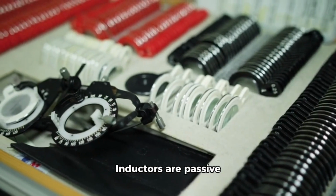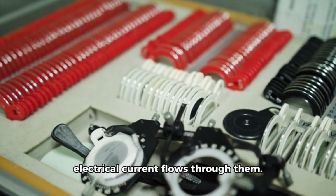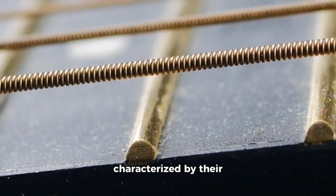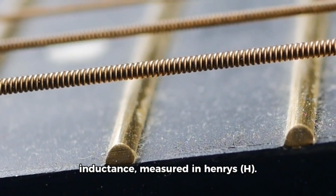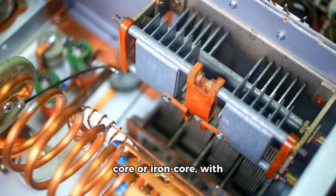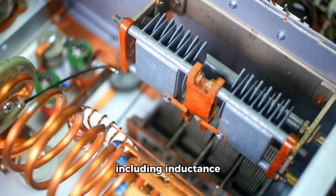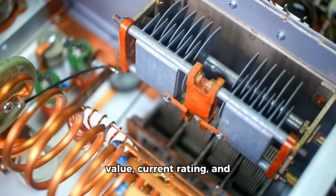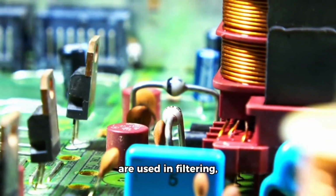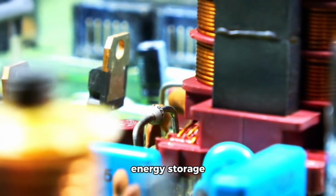Inductors are passive components that store energy in a magnetic field when electrical current flows through them. They are usually made up of coils of wire and are characterized by their inductance, measured in Henrys (H). Characteristics: inductors can be categorized as air core or iron core, with key specifications including inductance value, current rating, and quality factor Q. Applications: inductors are used in filtering, tuning circuits, transformers, and energy storage applications.